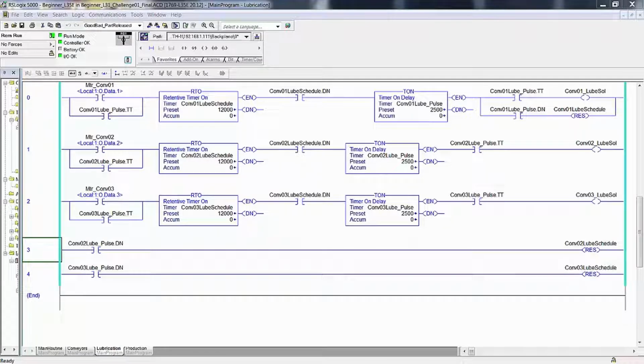because typically what happens is I get distracted by some point that I want to make, and then I don't necessarily get back smoothly to the sequence. Understand this: to simulate a part arriving at the entrance to a conveyor, you turn the photo eye to the on state, and it stays in that state until the conveyor motor energizes and pulls the part forward.